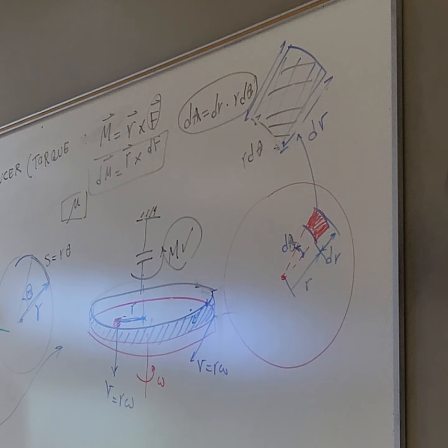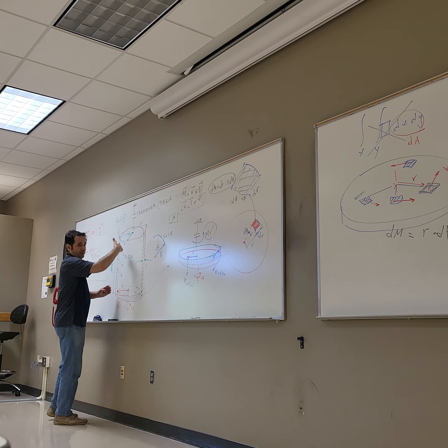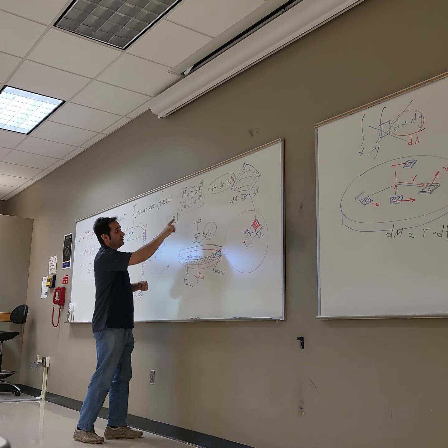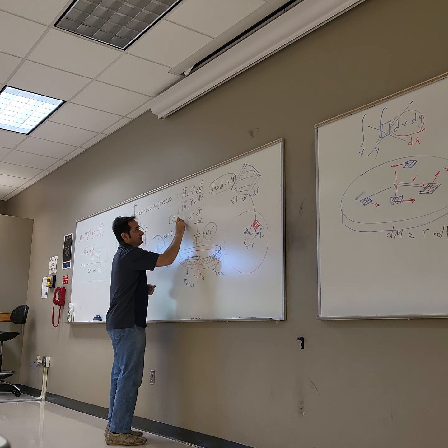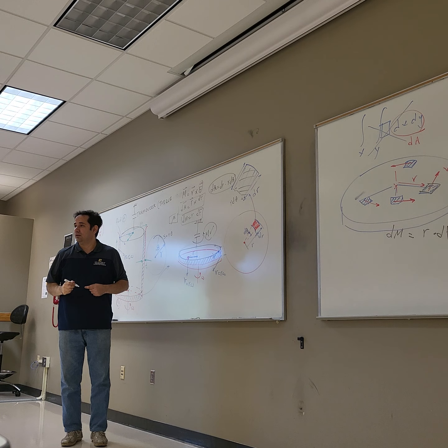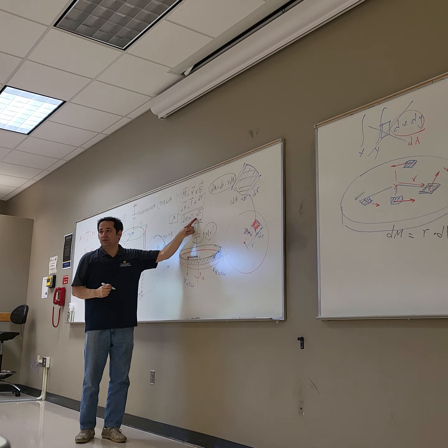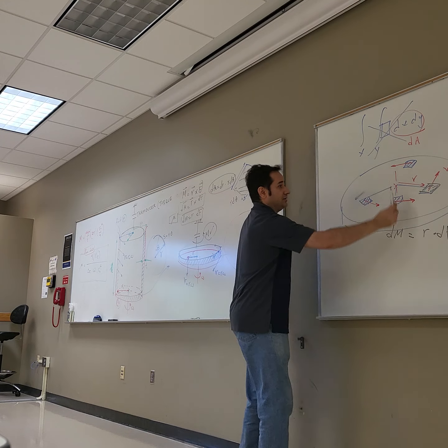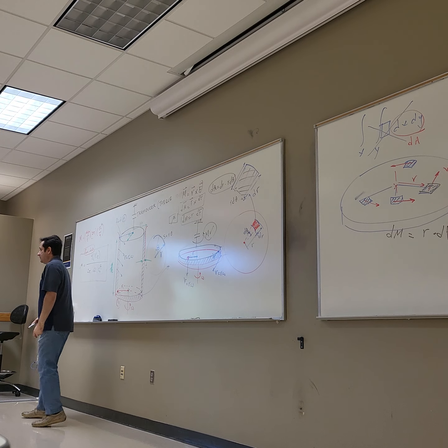force here, the friction force, the touch force, is in this plane, and the torque is in this plane. You see that? They are 90 degrees perpendicular. So instead of the cross product, I write r dF = dM. So it was extremely easy. Instead of a 3D vector cross product, I just did it because they were perpendicular and the moment is just in the z direction. And that's going to be the one that the sensor is reading.